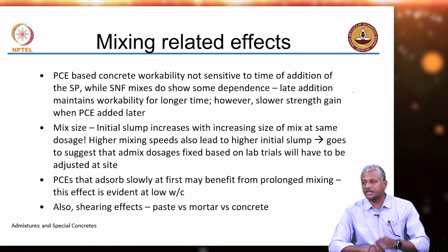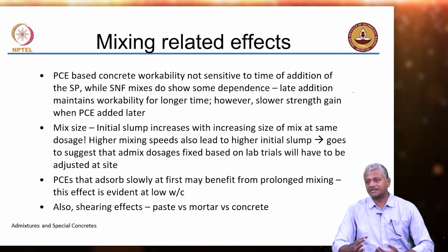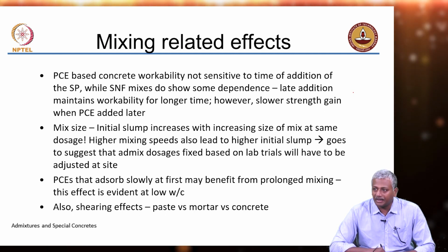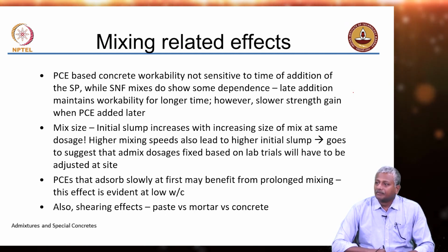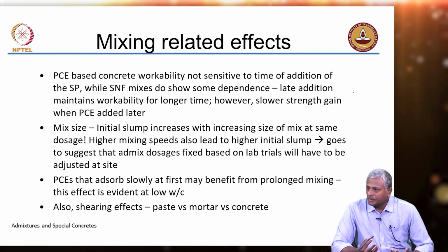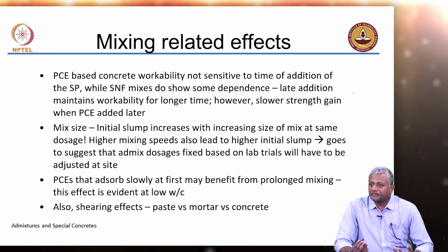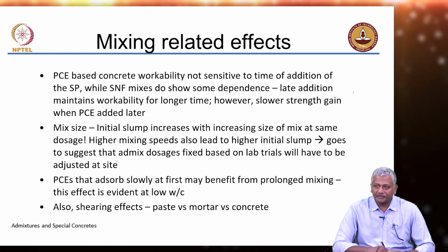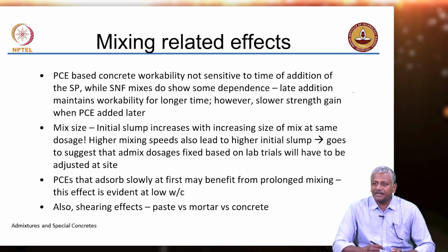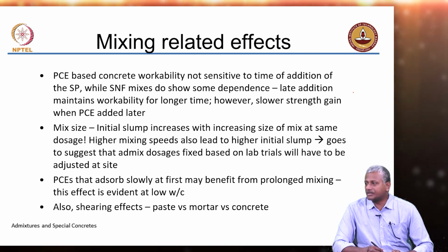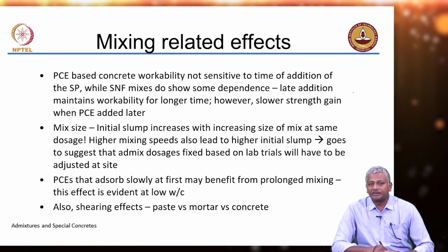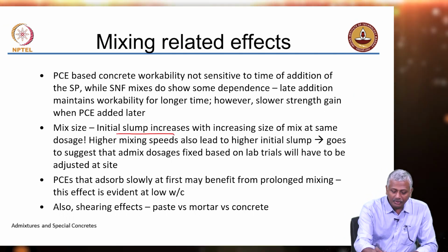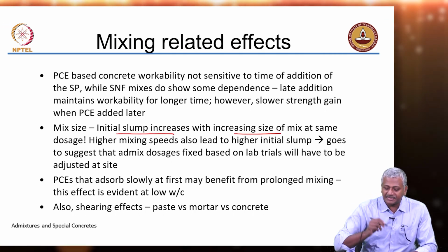Otherwise, you start losing its effectiveness fast, because the sulfonate from the SNF starts getting attracted towards the C3A, right. With PCE, this dependence is not as much, because there is no sulfonate in PCE, right. So, there is no competitive adsorption that happens with PCE. But if PCE is added late, it may lead to retardation, and that is what we saw from our concrete studies in the lab.